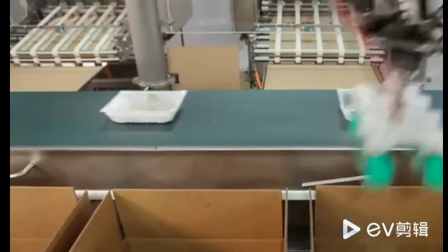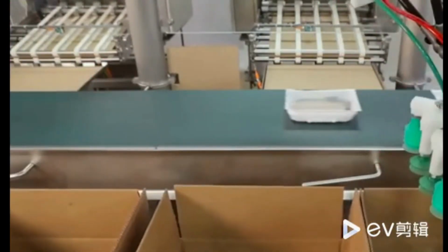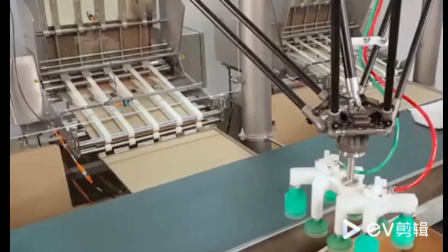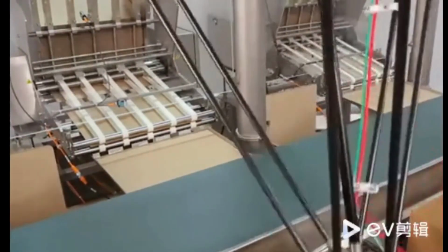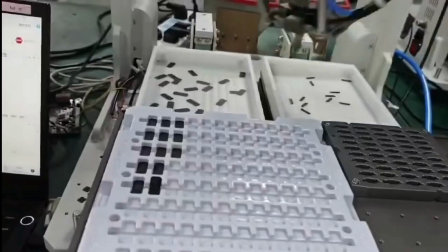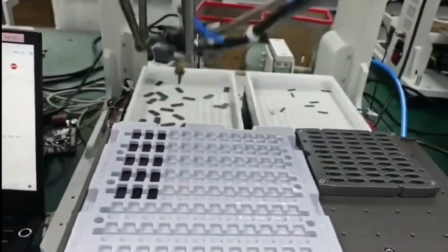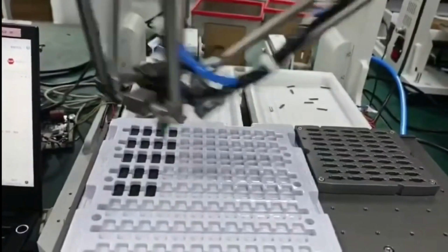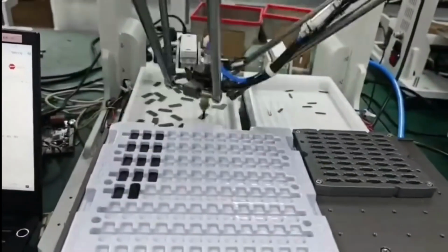Second, for larger Delta robots, the mounting structure is a real budget item. A large Delta robot needs a firm and substantial overhead structure to operate reliably. I have seen projects where this structural requirement was underestimated and added significant unplanned cost. For smaller Delta robots handling light payloads, the structure is straightforward and does not carry the same cost concern. Know which size range your application needs and plan your budget accordingly.